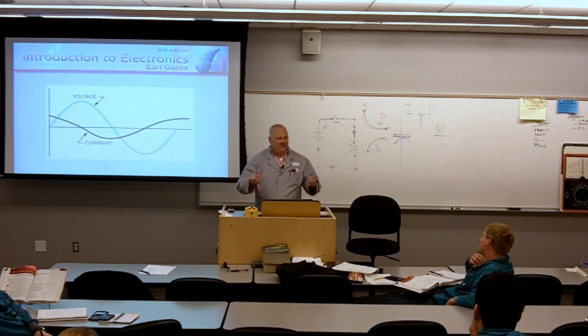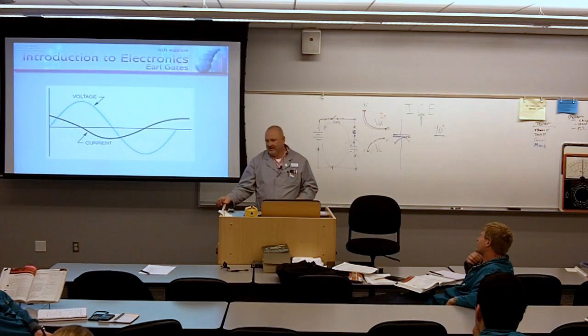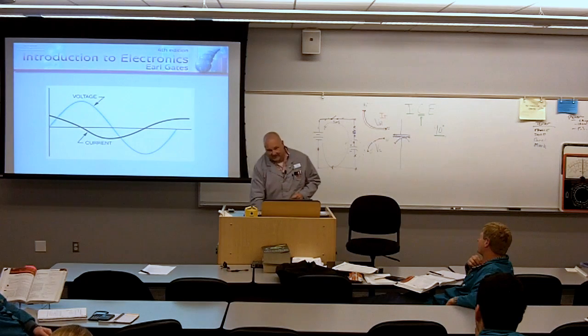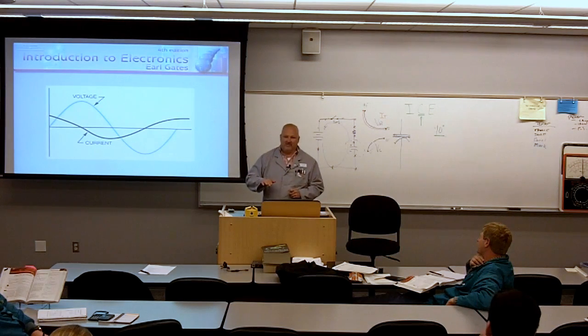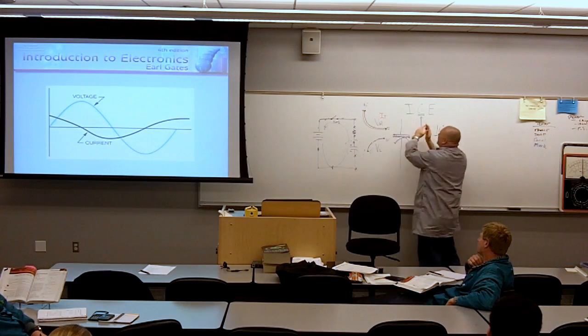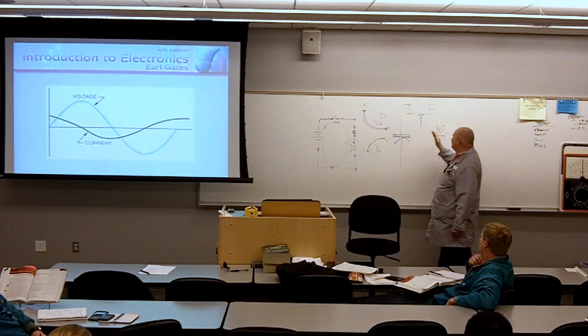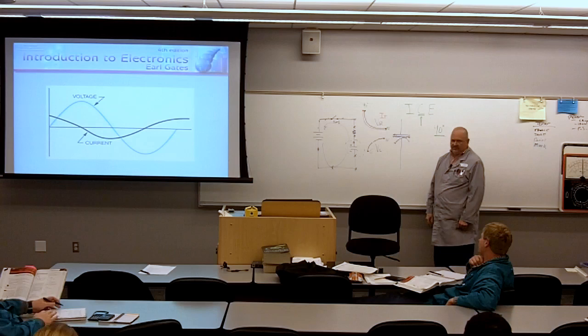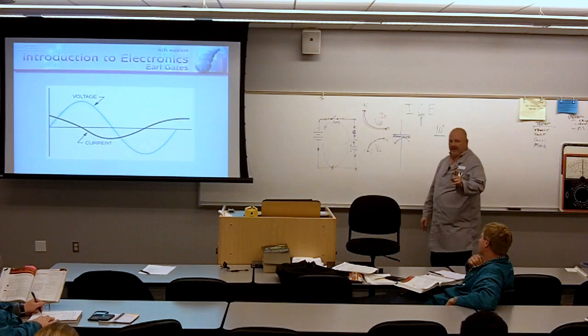So what is an AC waveform constantly doing? Constantly changing, and every 180 degrees it reverses itself, but it changes direction. First it's decreasing, then it's increasing in the negative alternation, then it's decreasing back to 0, and then it just repeats itself. In a pure capacitive circuit, current leads voltage by 90 degrees, period, end of story. Always 90 degrees, purely capacitive.